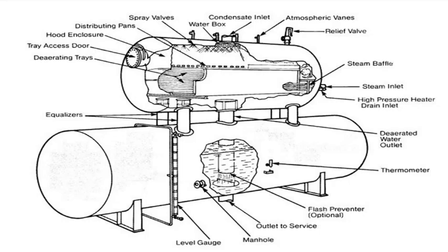So all the HP heater cascaded drains are connected to boiler feed tank, and LP heater outlet water condensate is coming to this deaerator, and after deaeration it is getting stored in the boiler feed tank, from where boiler feed pump is getting suction, and in some of the locations we have booster pumps also.